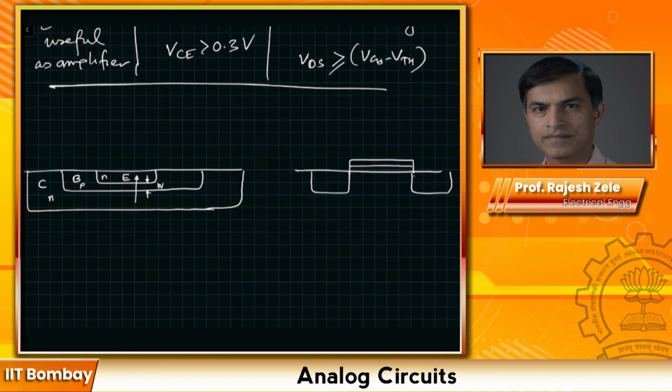It's like a sliver, if you remember the operation of bipolar, right? And that's what gives us the gain effect. Now, this width of the base region is really not controllable. Once you have a particular process, it's fixed. The only thing we can change is the area of the emitter, and that will change the property of the bipolar. So here we can also say that the transistor action is vertical.